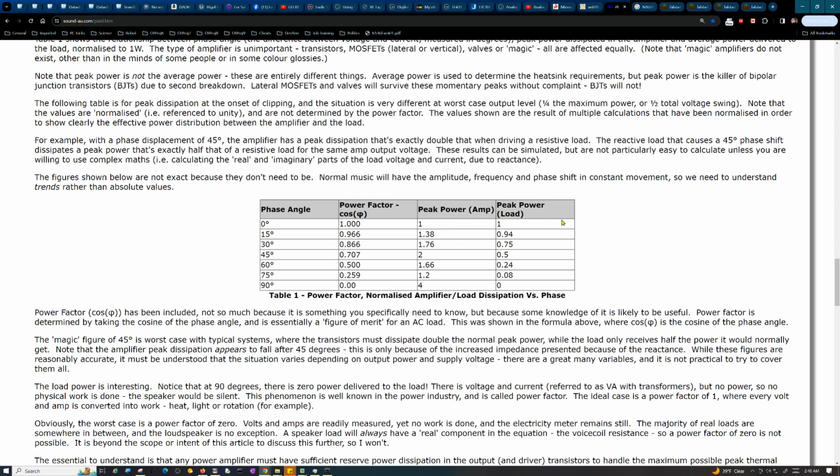So again, what he's saying here is that if you had a pure resistive load on your amplifier, a 50 watt transistor may do it. But in fact, because of the power factor problem with a purely inductive load, you would need like a 200 watt transistor, or better. But in practice, a lot of the time, like with speakers, he's saying it'd be somewhere in between, because you're never going to have a purely inductive speaker load, but you might if you're using it as a piece of test equipment, which is my interest.